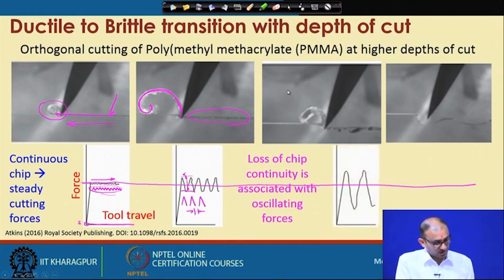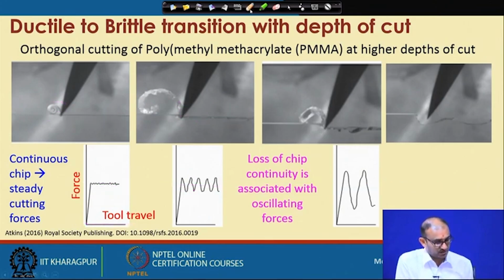Now, this is the third one. In this case, if you see the machined part, there is a large amount of deformation or fracture, or some type of unwanted features on the machined surface. The chip is also different now, coming in a very awkward form, so you are not able to identify the particular shape of the chips.